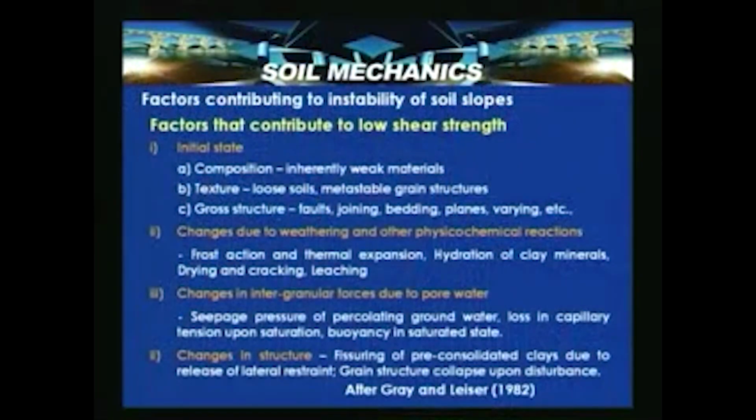Having seen those factors, let us see what the factors are that contribute to low shear strength. Ultimately, they cause the instability of a soil slope. Initial state, composition, inherent weak materials. If there are inherent weak materials, the composition can cause low shear strength.